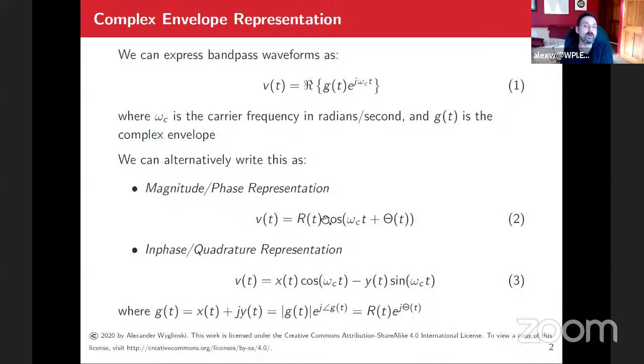So how do I do that? Well, just like the difference between Cartesian coordinates and magnitude phase, magnitude is going to be the square of the real plus the square of the imaginary, sum them up and then take their square root. And the phase, well, that's going to be equal to the imaginary component divided by the real component, and then we take the arctan of that.